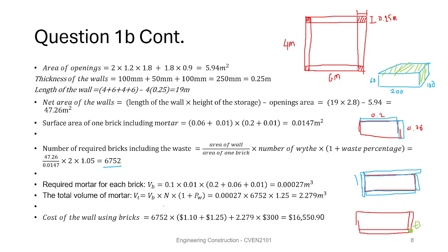So then from there, we know that each brick will require this certain amount of mortar. And then we know how many bricks we need to paste together. And then we know how much waste there is, which is 25%. So we can just simply calculate it that way, chuck it in your calculator.